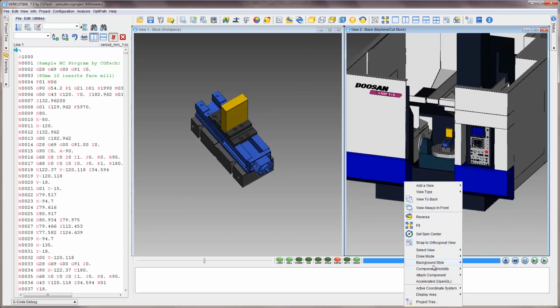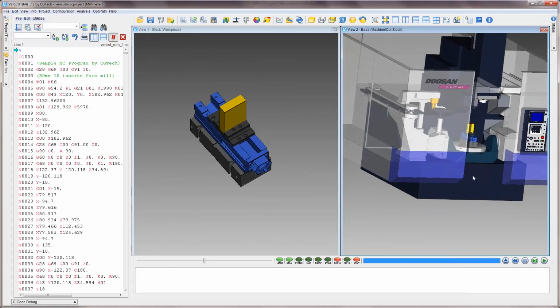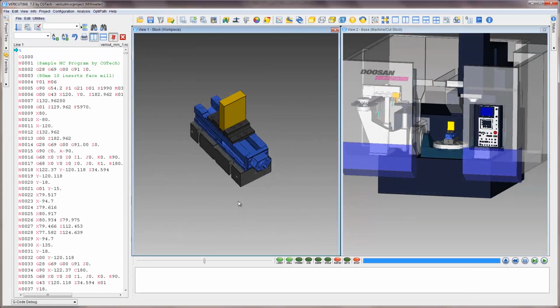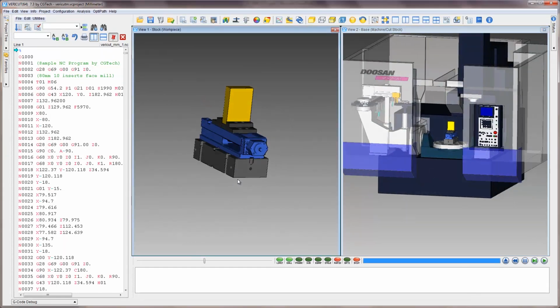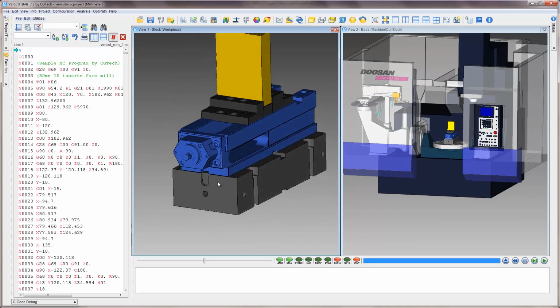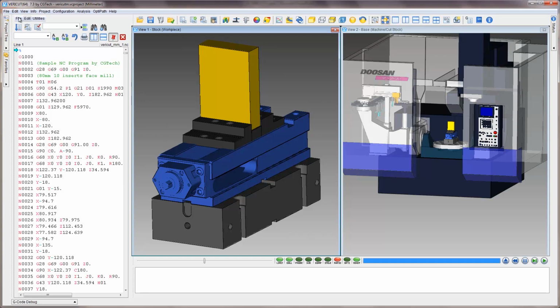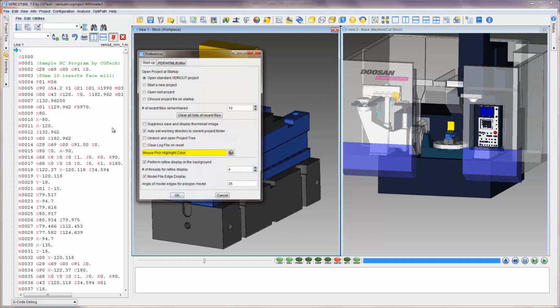If we put on accelerated graphics, we get that in the translucent view, but also in the cut stock view you can see that we have all the edges, so we can see what face is in front of which. So that's File, Preferences, Model File Display. I'd suggest leaving that on as the default.